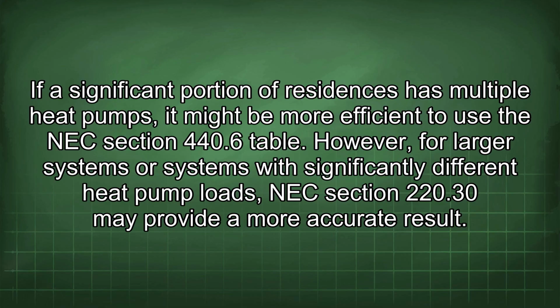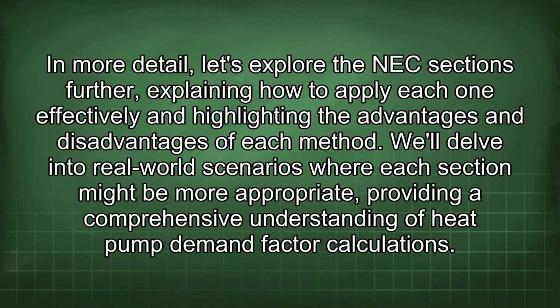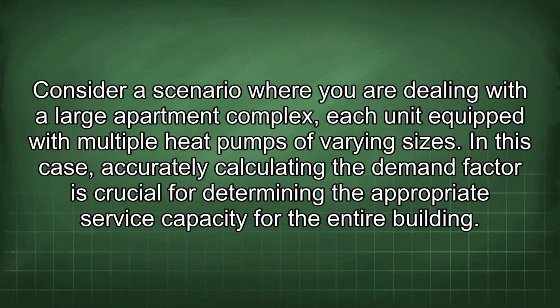more accurate result. In more detail, let's explore the NEC sections further, explaining how to apply each one effectively and highlighting the advantages and disadvantages of each method. We'll delve into real-world scenarios where each section might be more appropriate, providing a comprehensive understanding of heat pump demand factor calculations. Consider a scenario where you are dealing with a large apartment complex, each unit equipped with multiple heat pumps of varying sizes. In this case, accurately calculating the demand factor is crucial for determining the appropriate service capacity